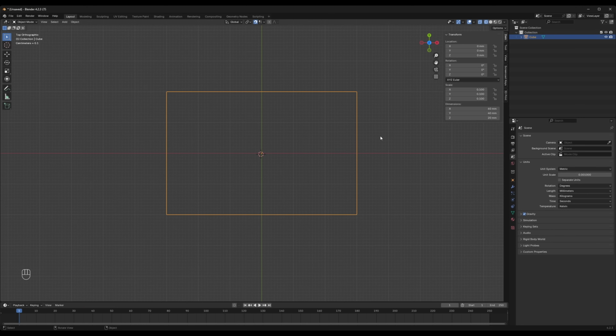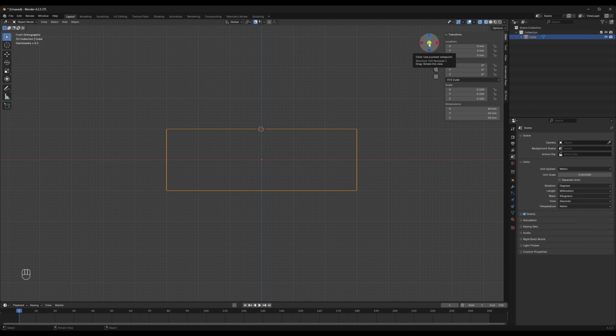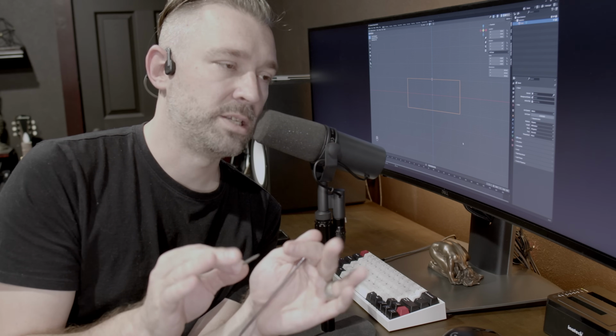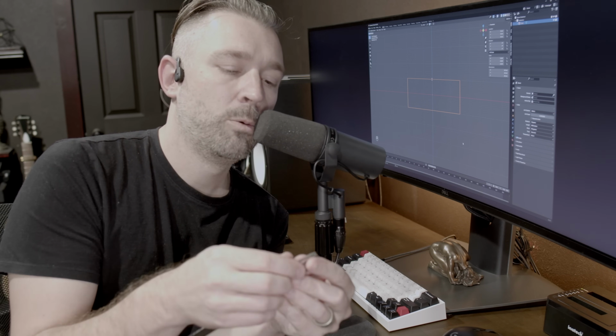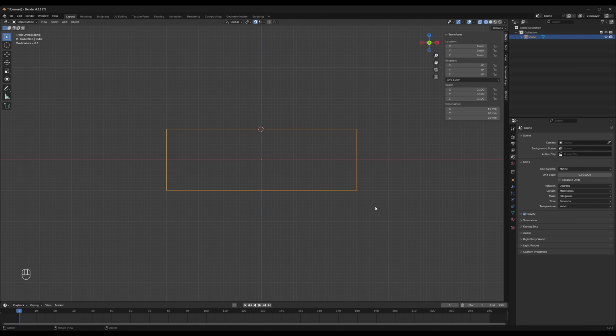The next thing we're going to do is switch axis over here to the y-axis. Now remember, negative y is towards the front of your build plate on your 3D printer. Since I'm going to be using a basic drywall screw to mount this to the bottom of the desk, I want to make sure that the bottom of the mount is thick enough so that when we screw through it, the top of the screw is not going to come through the top of my desk and damage anything. And right here, we have this at 33 millimeters. So we'll make the mount thick enough so when I screw this through, it doesn't pop through the other side of the wood.